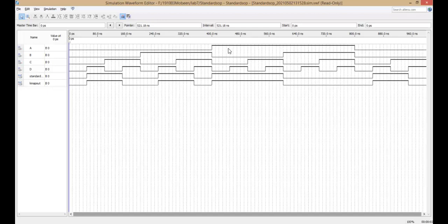After that, to get the output 1 or high at A, either A alone has to be high, or A has to be high with C or D or both of them. Now after that, if the A is high with B, you can see that there is a low at the output, which basically confirms that the truth table is verified with the equation, and the Kmap equation is a simpler, more effective and practical procedure to work with these truth tables and equations.